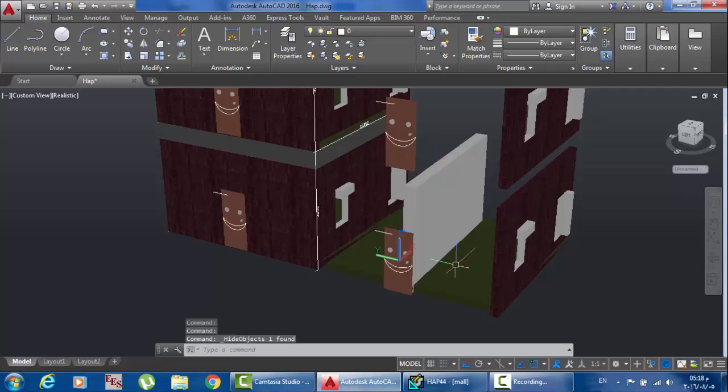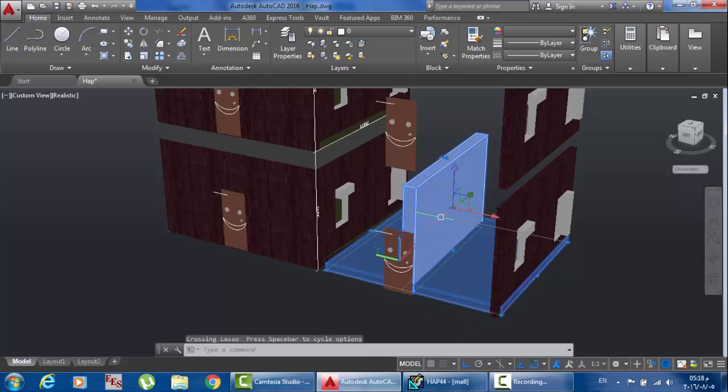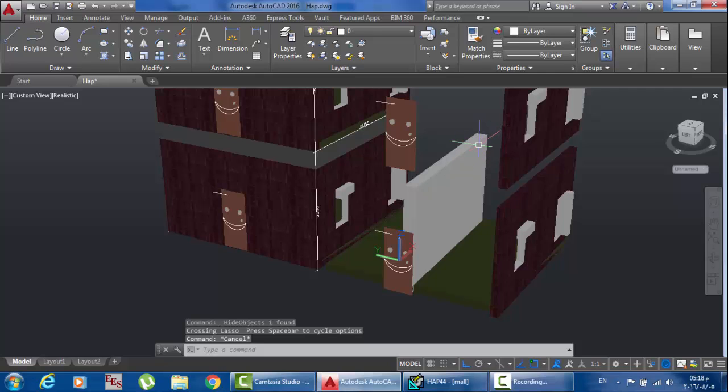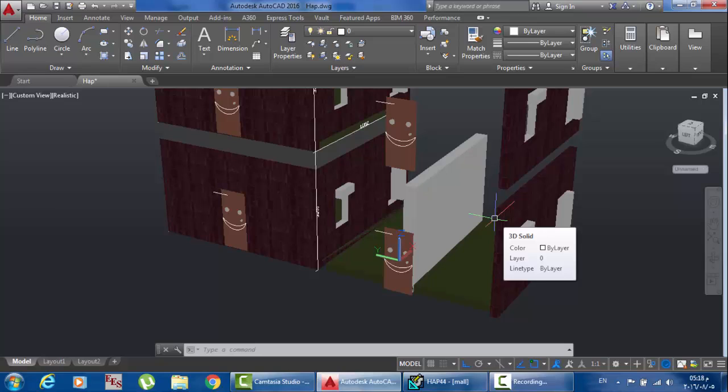This partition is not exposed to the sunlight; it is an internal wall, and you have to determine its area. The area is this length times this height, or the full area of heat transfer. The heat transfer equation is the area of the partition multiplied by the U of the partition multiplied by the delta T between this conditioned space and this unconditioned space.